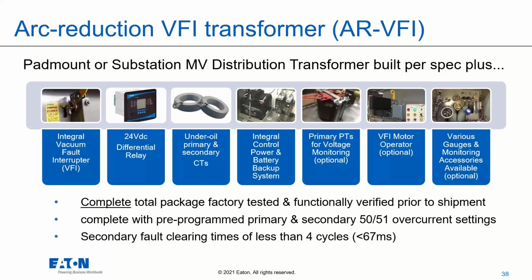And this can be something that's usually overlooked. It can be kind of difficult to source the power on site if there's no 120 volt source available to power all the equipment. So including that integrated power into the transformer and the control box is a convenient feature. And then along with having that battery backup or UPS system is really just to ensure that the relay can perform its self-diagnostics and really control the transformer for the duration of an outage.